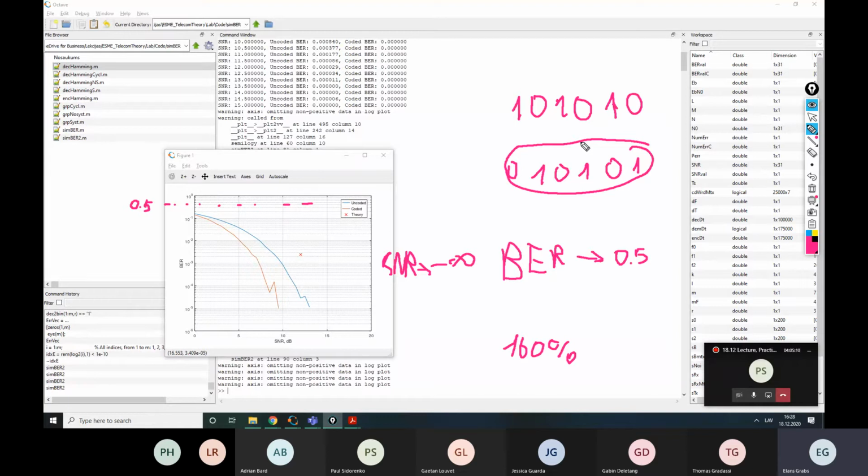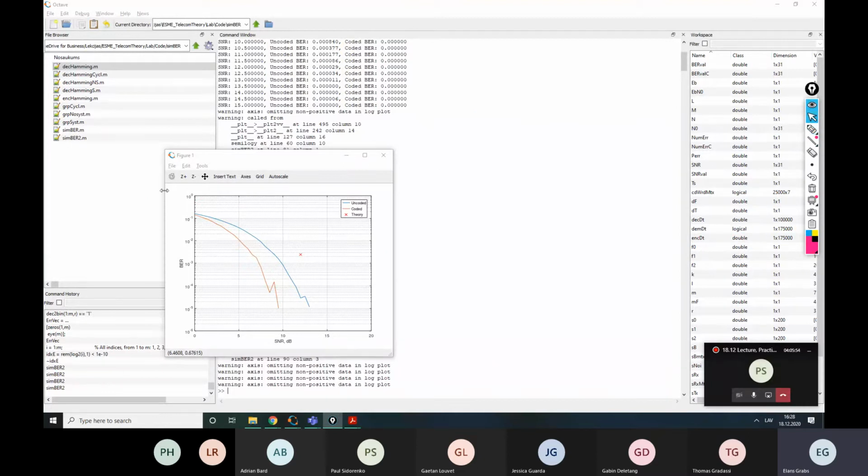That would be nice if it was so, but unfortunately, actually, the error probability is close to 50%. So it's absolute chaos. Yes. There is no way to find out if there is an error in a symbol or not. And that is the worst case scenario, which happens only if we have a very weak signal and a very bad channel, right? So that is something to keep in mind, that this error probability will never achieve 100% here. It will always strive to achieve 50%. And that is normal, right? So I will keep this frequency shift keying for now.